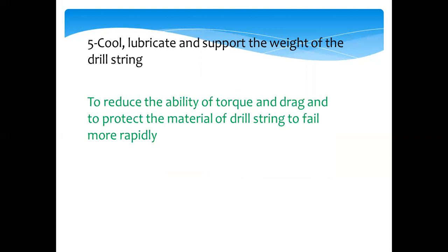Okay, because if we don't lubricate the drill string and bit, they will fail more rapidly, because as we know, the drill string and bit and the BHA are metal, and the metal stiffness and strength get reduced with high temperature as we drill deeper. So that will allow them to drill longer interval runs. Okay.